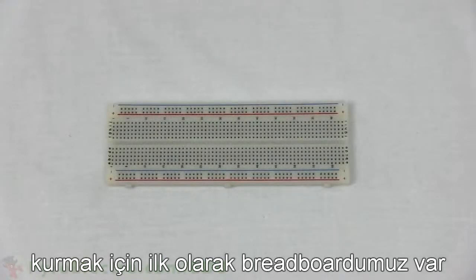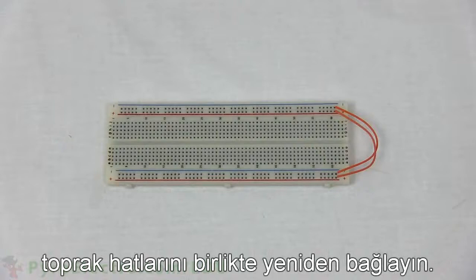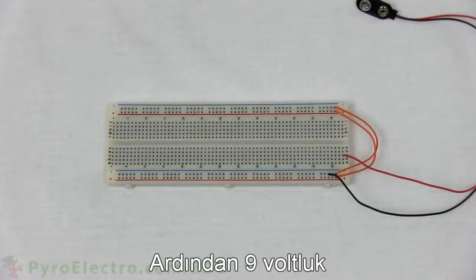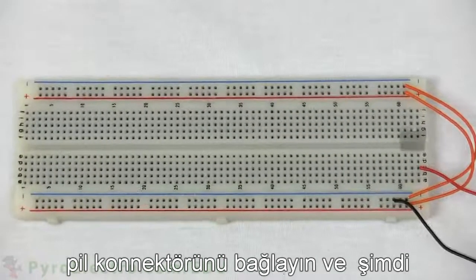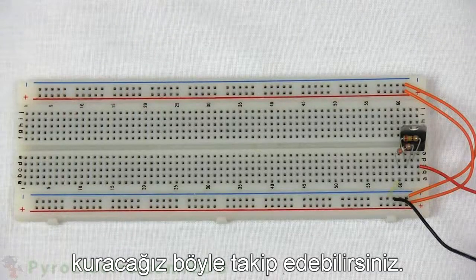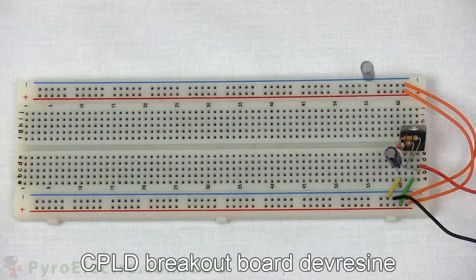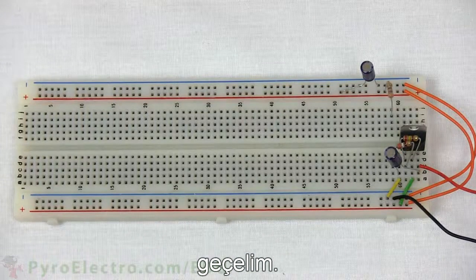And now let's build the circuit. To build the circuit, first we have our breadboard. We connect the power and ground bus lines on opposite sides of the breadboard together, followed by connecting the 9-volt battery connector. And now we'll build the circuit using a part-by-part time lapse so that you can follow along. First we start with the power regulation circuit, then we move on to the CPLD breakout board circuit.